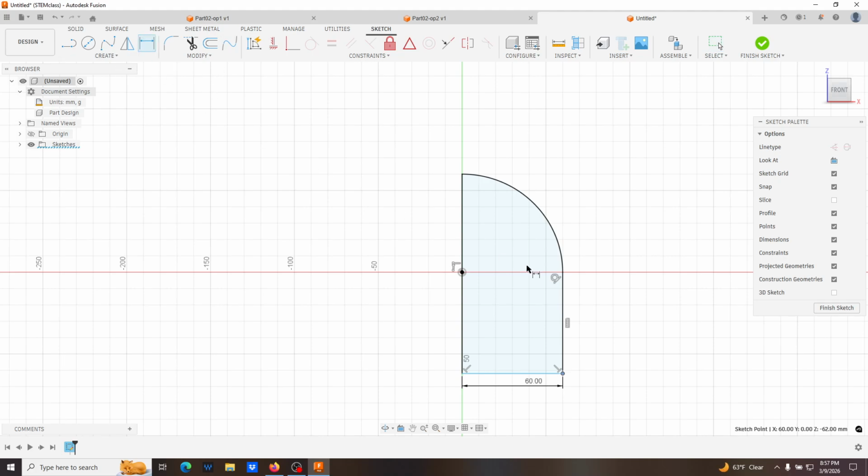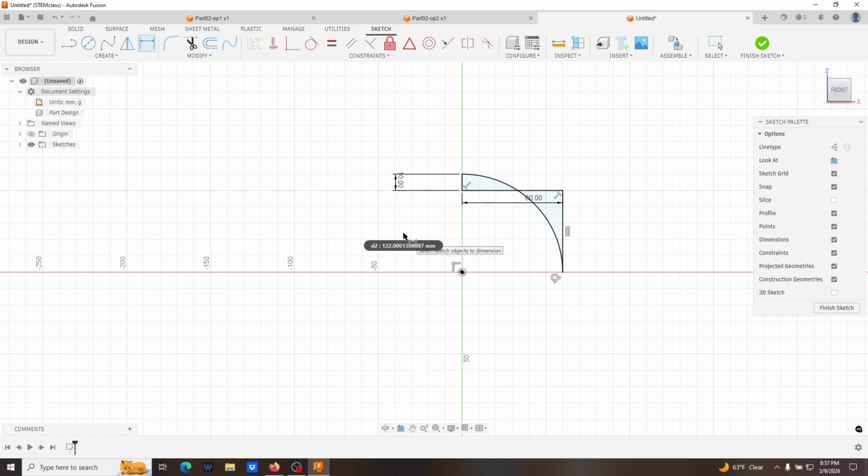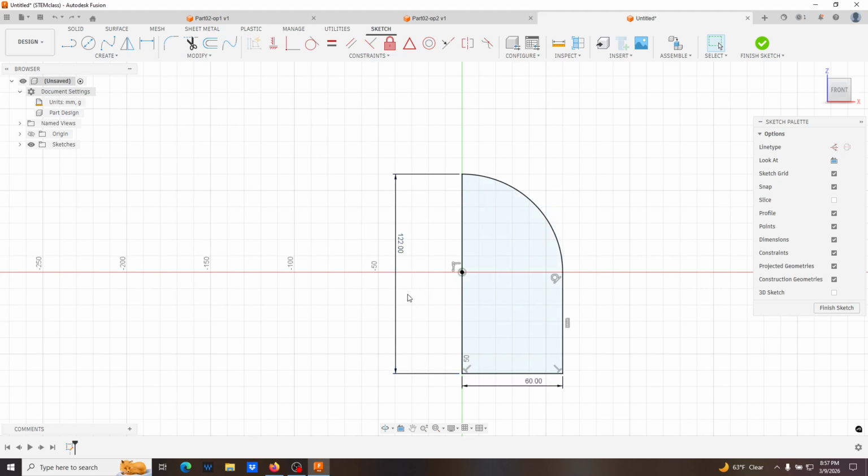Okay, so I'm just going to go here and I'll click this edge. Oops. And that's also a really important thing. One of the things that's really important is you want to clear your selection every once in a while, because I thought I was just dimensioning this, but I still had something selected. So you'll see that you have the blue edges. I like the escape key just to clear what I have selected. So now if I go back to my dimension tool and I click that edge, then I can pull back. Okay, boom, I'm at 100. Oh, no, that put 10. Messed that up. Okay, so I'll put that as 100.